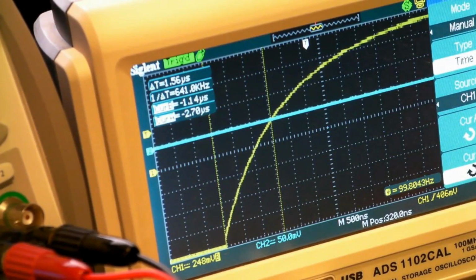All right. So the output of the Agilent waveform generator is a very, very fast edge. It is not as slow as 2 or 3 microseconds. It's in the range of picoseconds or nanoseconds. Sorry, not picoseconds. It's in the range of nanoseconds. So what is causing this? Well, the oscilloscope probe is basically what's causing this.